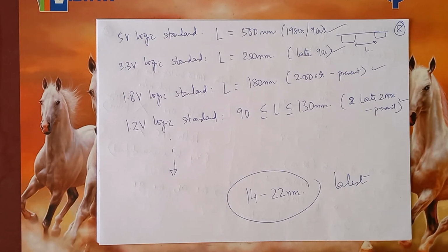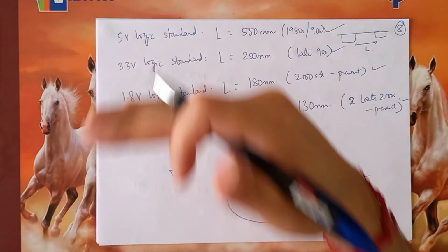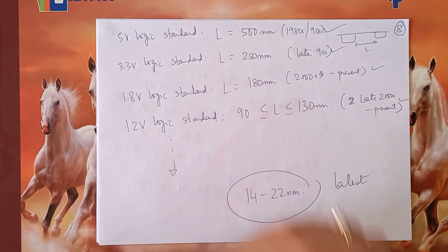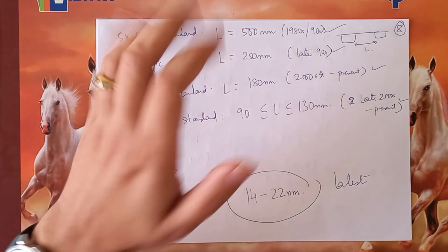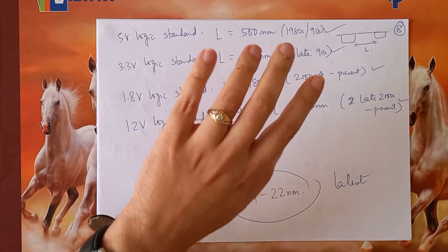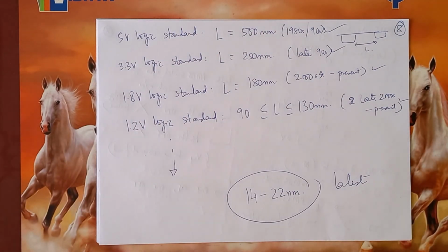So in today's lecture, we saw how we can use the MOSFET like a switch and how we can build different logic circuits. We saw, to be precise, the NOT gate and the universal gates NAND and NOR, and how to make them using MOSFETs. In particular, this technology is called CMOS technology. Thereafter, we saw how much the CMOS technology has improved over the years, where the transistors are becoming smaller and smaller without losing too much of their original properties.